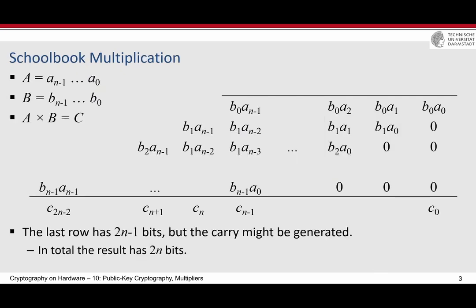We know that this is pretty large. We know how many adders you need if you want to implement an adder at every stage. Of course, you don't need the adder at every stage because some values are actually 0 here. But if you implement this in a schoolbook way, then you need n minus 1 adders, and each stage of the adder at least needs two n-bit values, or in some cases n plus 1 bits.